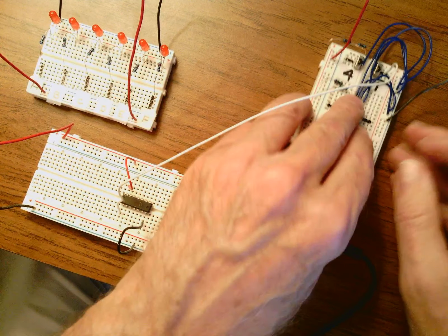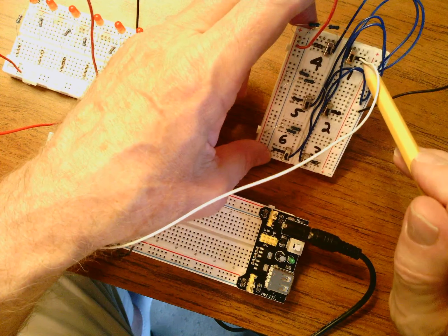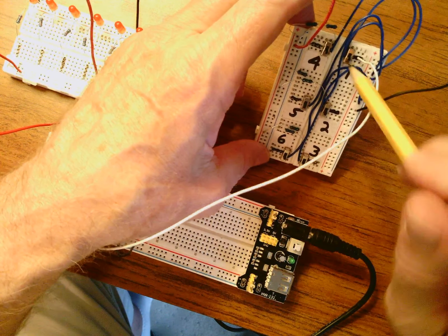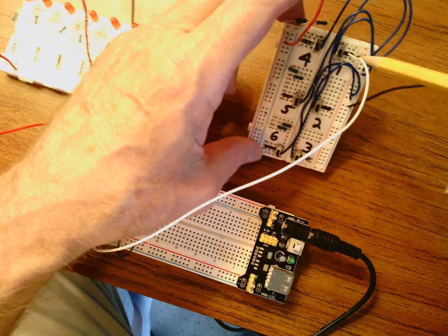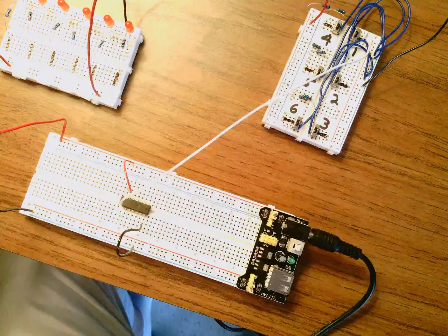I don't know how easy you can see it. Let's see if I can show you this. I explained this before, but there's switch 1, and when it's down, you have 0 volts. When I push this slide switch up, I'll have plus 5 volts on the output of the switch. The output is the center pin of these 3 pins. So I'm just going to go from the output of that switch to pin 1.